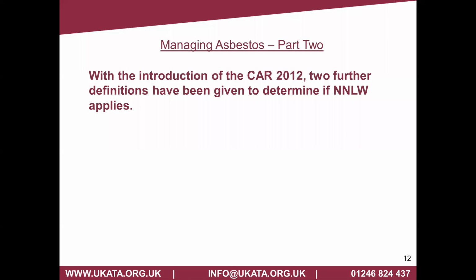For example, where a panel had to be removed, let's say an asbestos insulation board panel, and it was going to take less than 1 hour to access a valve to repair a leak behind a box-in, the works would be classed as non-licensed because it could be done under short duration maintenance works. And of course, the panel would then have to be removed. It's advisable that it would then be disposed of.